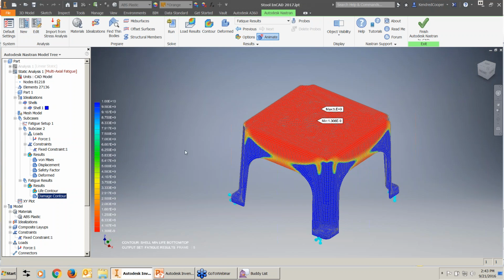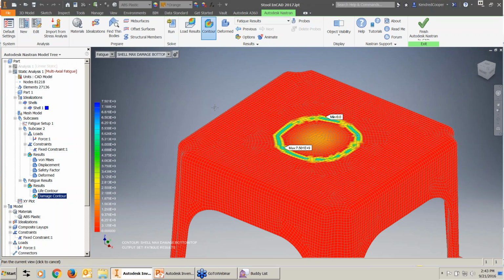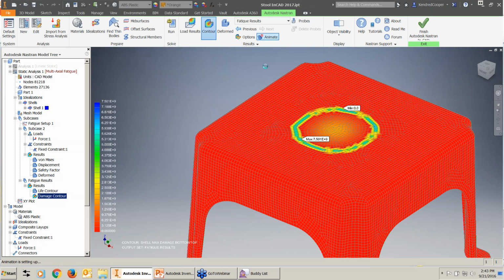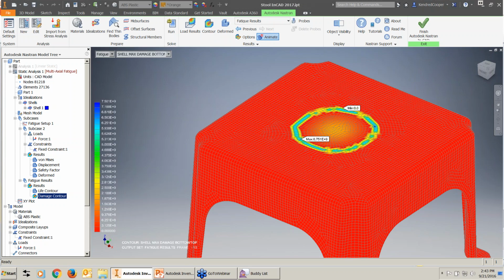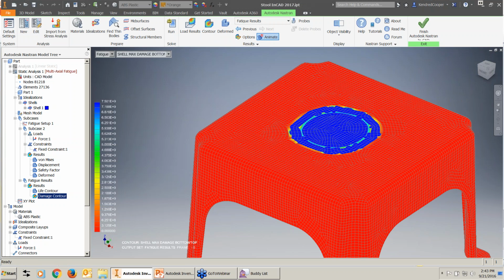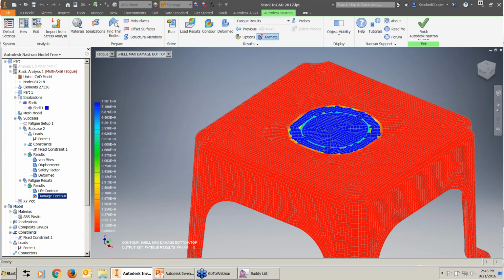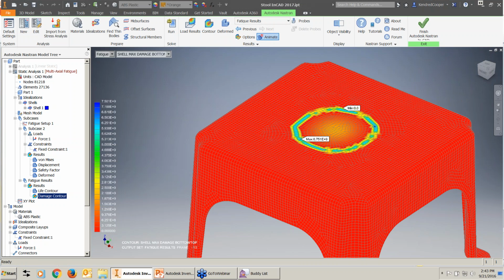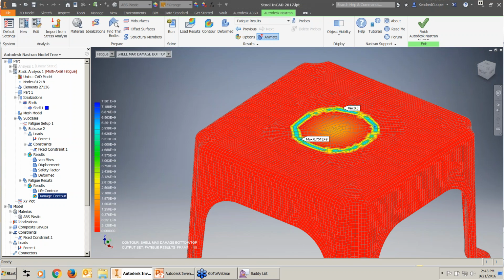The last contour is the damage contour. This gives you your localized region or localized area of damage. So as you press your foot on there, really the surface of the table that contacts your foot is getting some reinforcement from your foot. So right under your foot is not necessarily going to break, but right around the outer edges, there's your weak areas, and that's what the outline is showing here. When this material breaks, it's going to break in those areas.